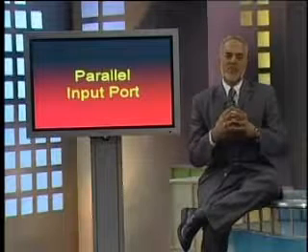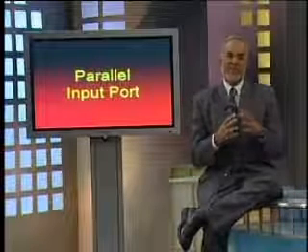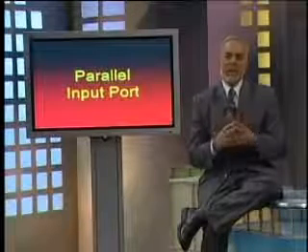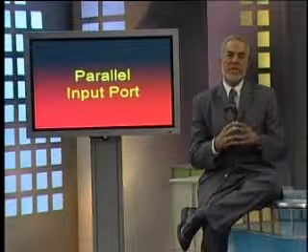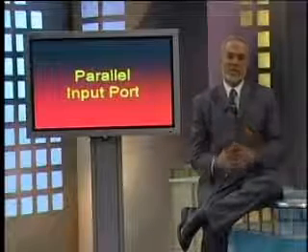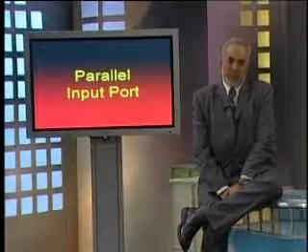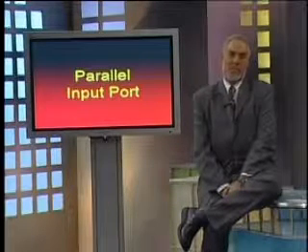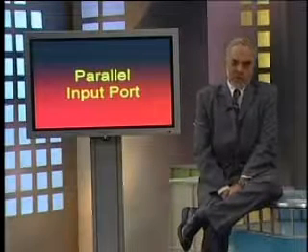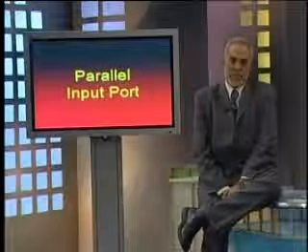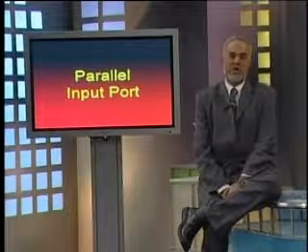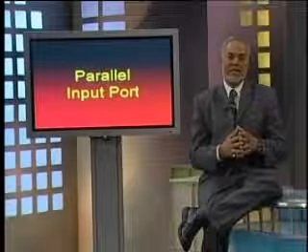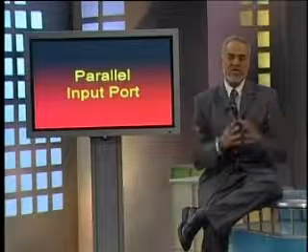We also see that the output enable is low active, so we need another inverter at the output of this AND gate. For this particular example, the data would come from the peripheral devices through the tri-state buffers onto the data bus of Falcon A. The data bus of Falcon A is 16-bit wide.